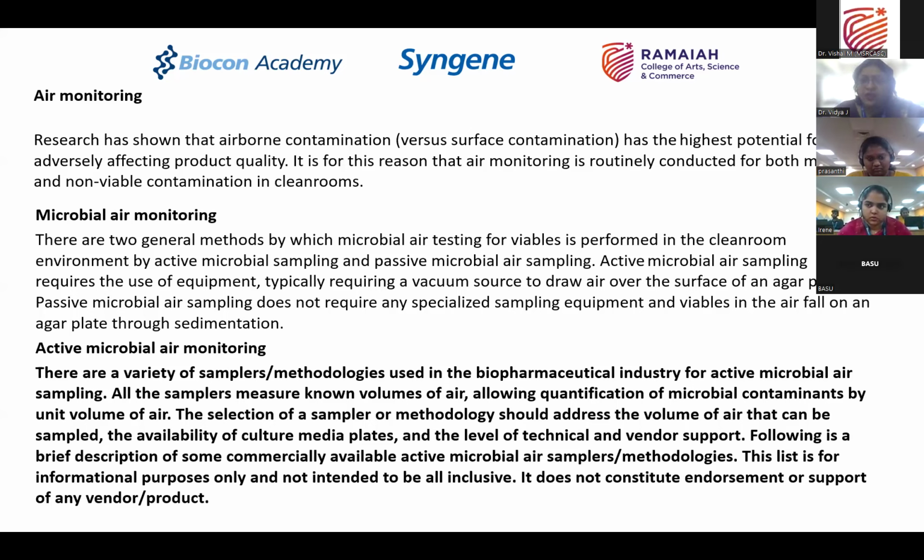So I think air monitoring, I told you already. Any airborne contamination, so air monitoring, you have to do it for both viable and non-viable contamination in the clean room. Then microbial air monitoring, so you have different samplers. All these you have to keep checking. And active microbial air monitoring.